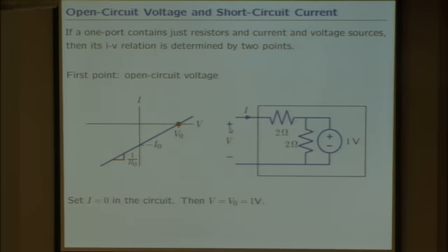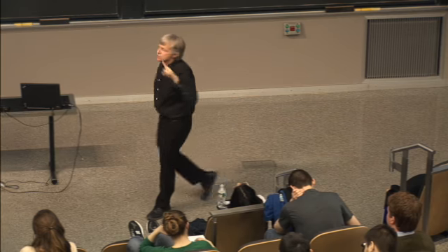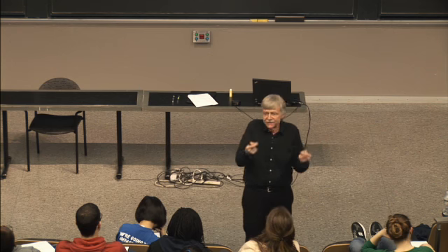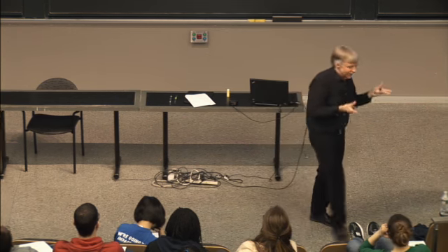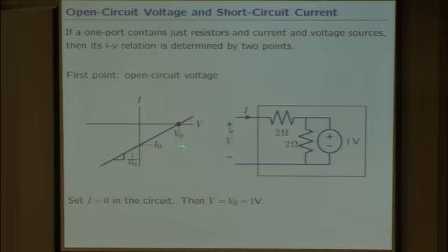And that's because 2 points determine a straight line. I know by having proved it, by using linear algebra, that the solution is a straight line. I know from geometry that 2 points determine a straight line. I only need to find out 2 points. So by convention, the easiest 2 points is usually the simplest cases. Set the voltage to 0 and set the current to be 0. So that motivates the idea that if I have an arbitrary circuit, if I want to figure out this reduced complexity abstraction, say I want to make a Thevenin equivalent, what I would do is first ask the question, how big is the open circuit voltage?